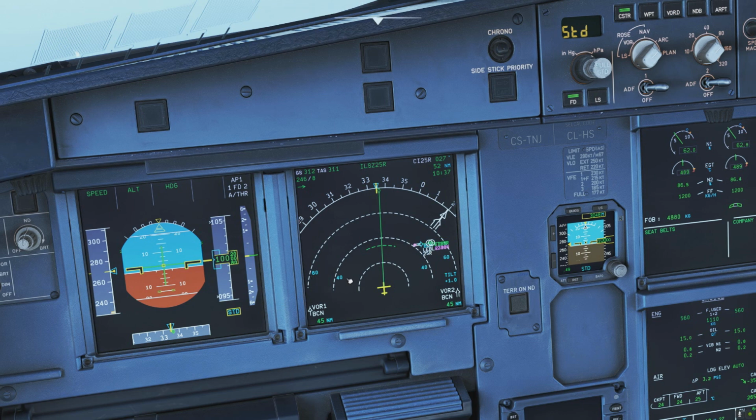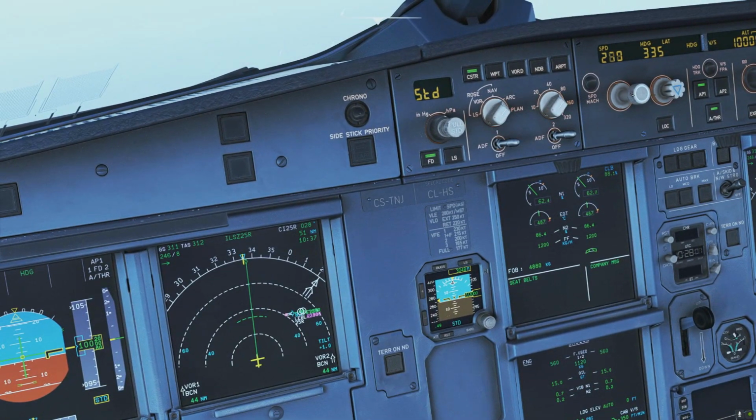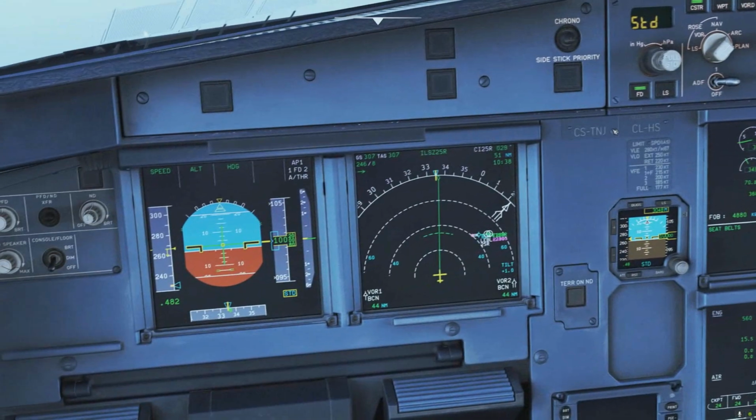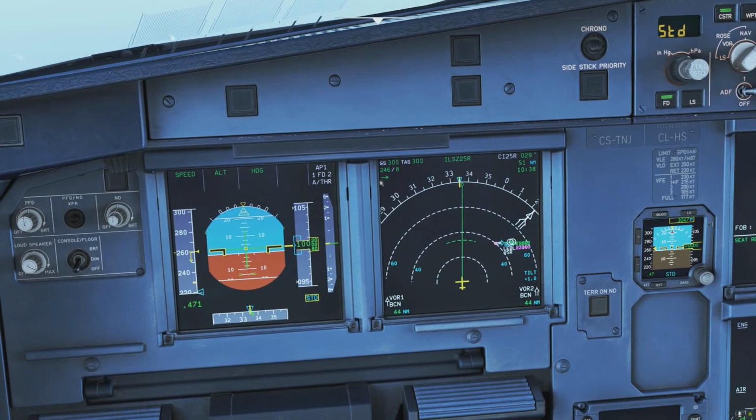That already tells me that we're going to end up being high, because we're at 10,000 feet and getting closer and closer to the runway. One thing you can do to think ahead is to reduce the speed. So I would go back to something maybe like 230 knots, maybe even 220. At some airspaces you need to first clarify this with ATC. Most of the time you don't. After all, you're the pilot, you need to manage the energy of the aircraft.